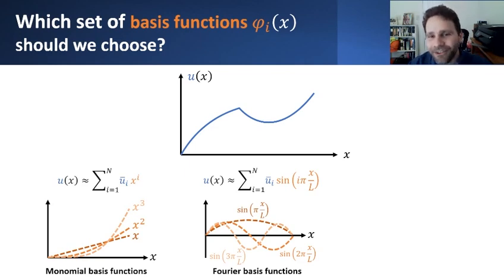So they too are a nice starting point, but they don't necessarily have a lot of utility in these particular problems, where if I really want to represent just a constant, I have a hard time representing just a constant function with a finite number of truncated Fourier basis functions. So they may be good for representing nice wavy signals in other kinds of domains, but in mechanics they're not always a great starting point, at least not for quasi-static problems.